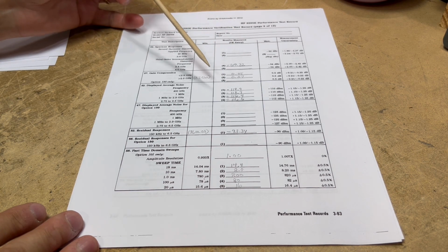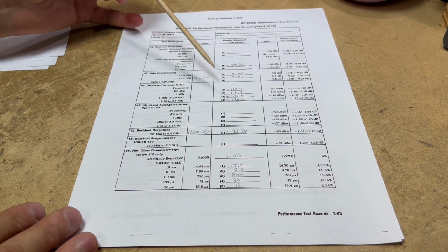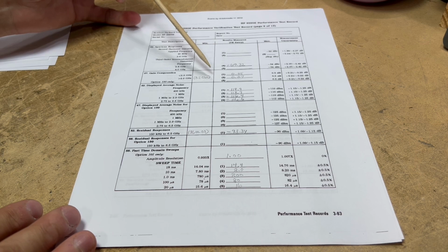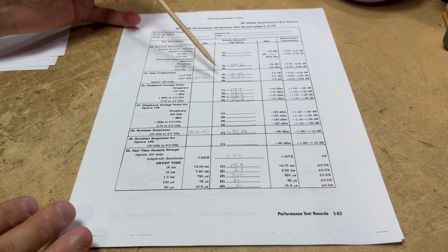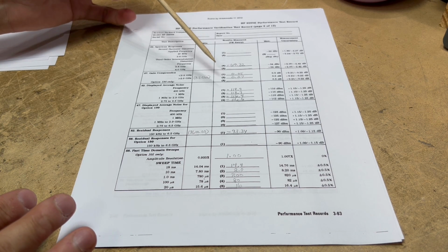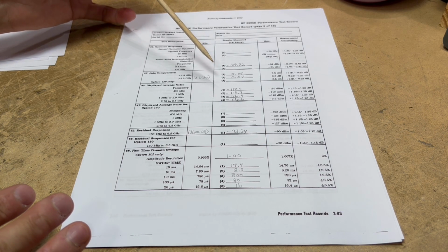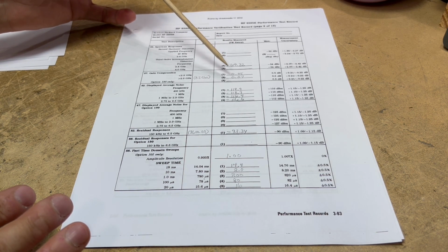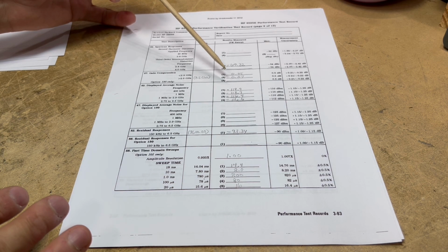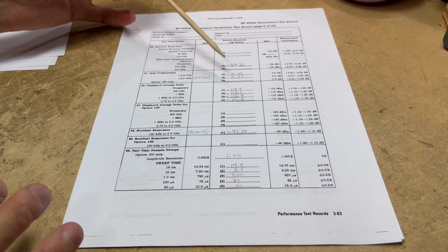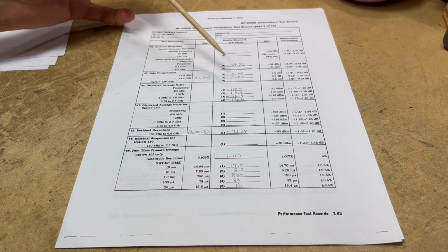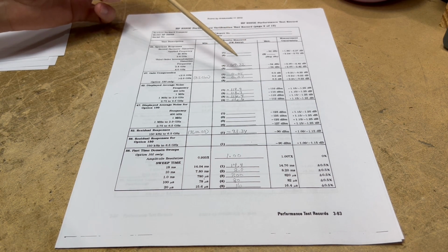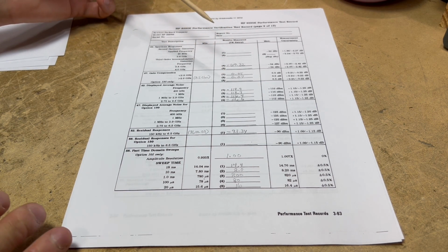Measured gain compression. The gain compression was one of the measurements I wasn't able to perform exactly as directed, because I don't have two signal sources that will go to 4 gigahertz. I tried using the HP 8620C, the sweeper unit, and the frequency was just too unstable to get a meaningful reading. So what I ended up doing was doing the same measurement